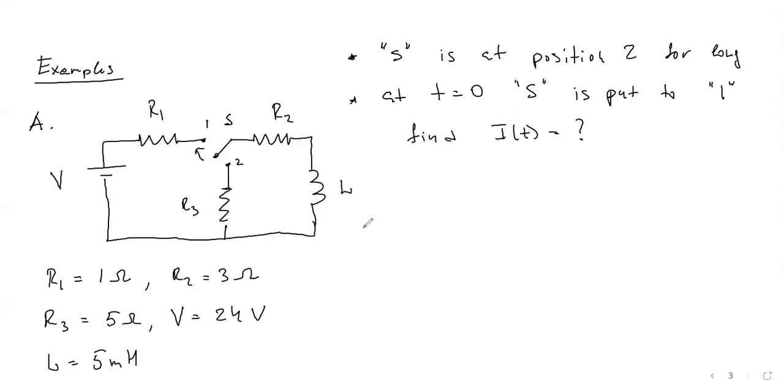Okay, so then in this case, I can write the solution for the charging process. Assuming that the initial current was 0, the current would be I max multiplied by 1 minus exponent minus t over tau. That's it. We solved the problem, yeah? At least for the first part. And what is the I max in this case?